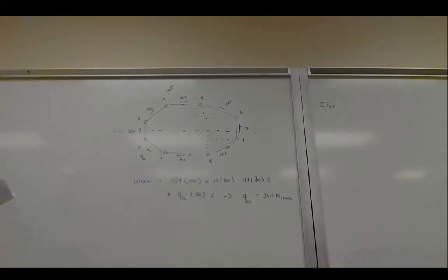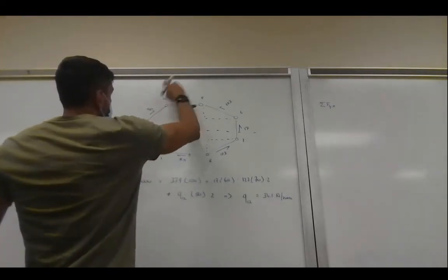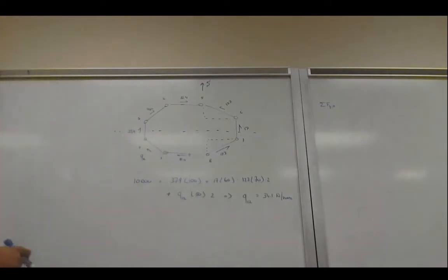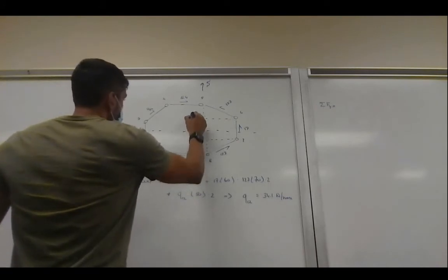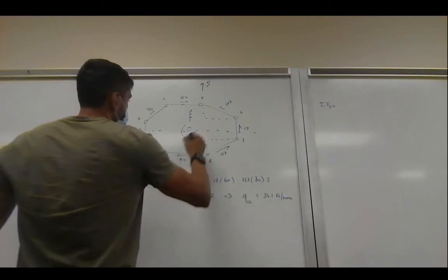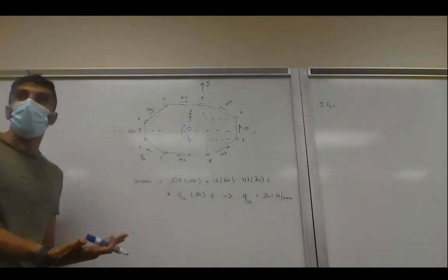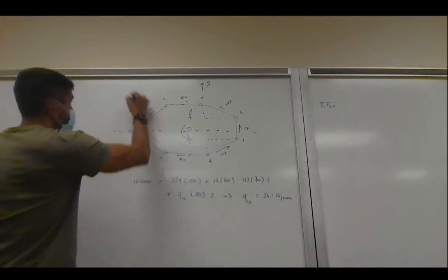But yeah, the next question was, okay, what if we move S to here? What happens? What you can do is say, well, everything remains the same. I determine my shear center, place S in the shear center, and add a torsion to it. Again, you would have one equation, one unknown, and you could resolve it. What you would see is that the direction of 1, 2 remains the same.